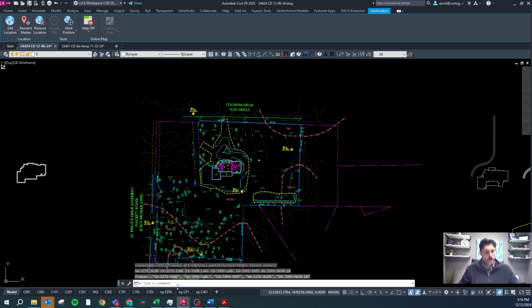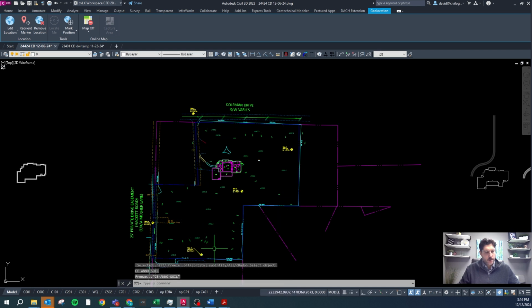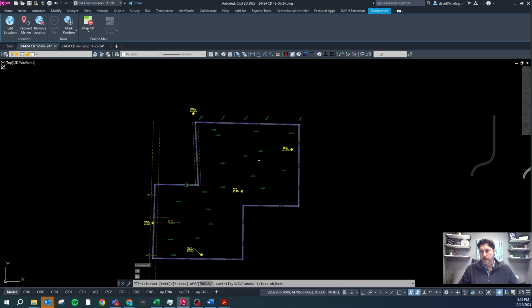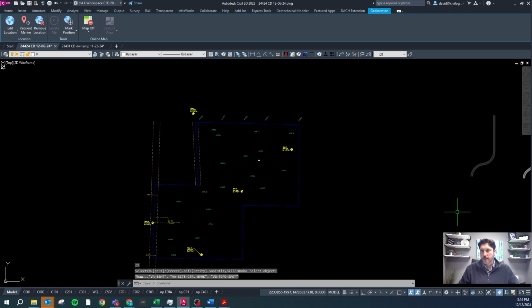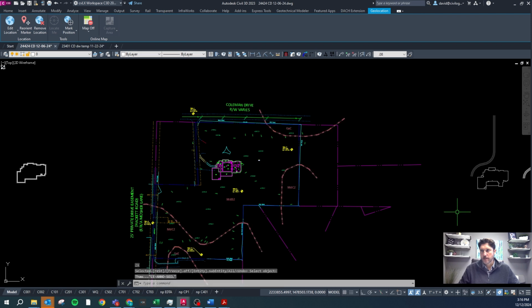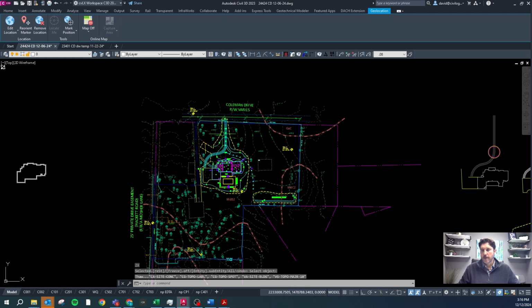it's going to turn those things on or off. I turn those again, and I can turn a couple more things off, a couple more things off. And then I can go over here, type S, and toggle to rest, and now it's going to turn the rest of the stuff off other than those 3 or 4 things that I just clicked. And now I can turn everything off except for that. And what's so powerful about this command is I can come off to the side, run it again by right-clicking. If I don't select anything, it backs up one step, backs up another step, backs up another step, backs up another step. So you can see how this will be very powerful when you're converting surveys. So remember that command and get to know it. It works really well.